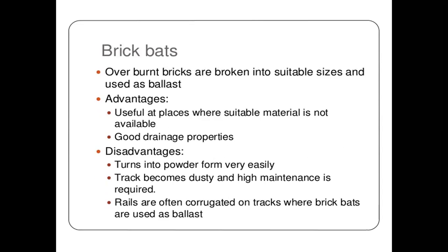The brickbats. Overburnt bricks are broken into suitable sizes and used as a ballast. The major advantages of using brickbats as a ballast are that they are useful at places where suitable material is not available, and they possess good drainage properties.